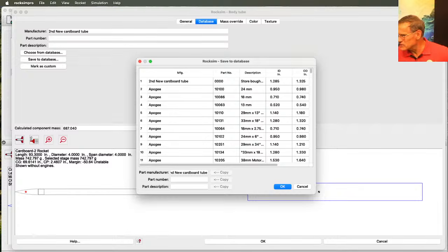DK says, Tim, after I use the rule of thumb of thrust equals 5 times the weight and CP minus CG divided by the diameter is greater than 1, do I need to know anything else to ensure stability as the rocket leaves the launch rod?